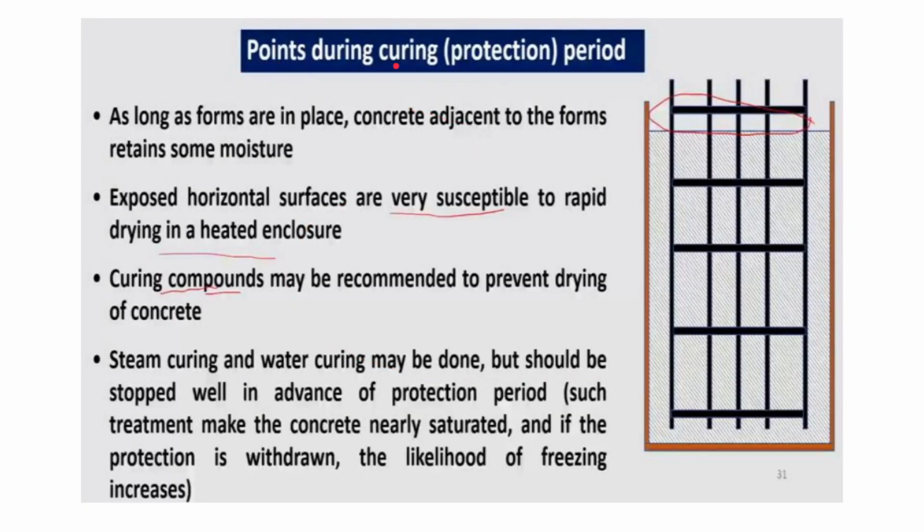Some of the points to be followed during the curing protection period are: as long as forms are in place, the concrete adjacent to the forms also retains some moisture due to the contact. The exposed horizontal surfaces are very susceptible to rapid drying in a heated enclosure. Because of the heating, they are also susceptible to rapid drying. So curing compounds may be recommended to prevent drying of concrete. These are also essential.